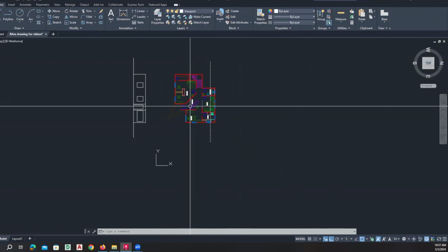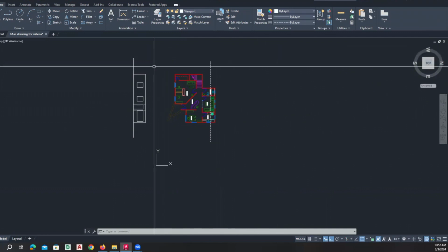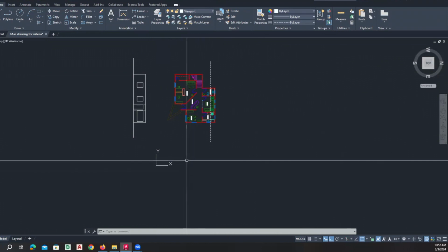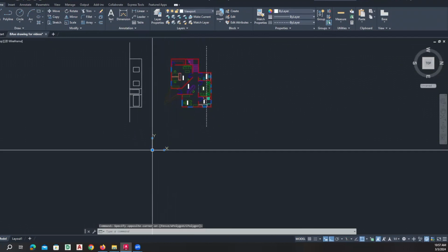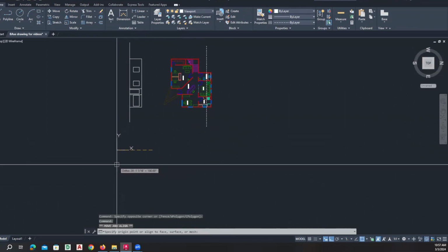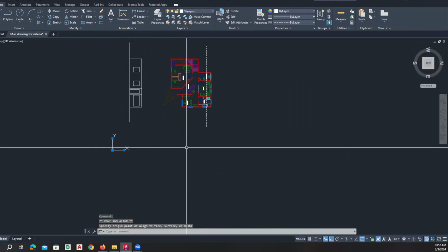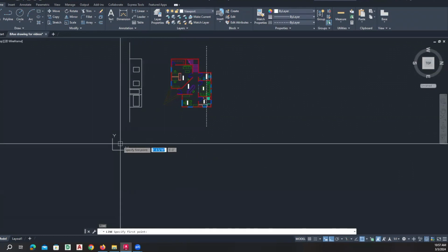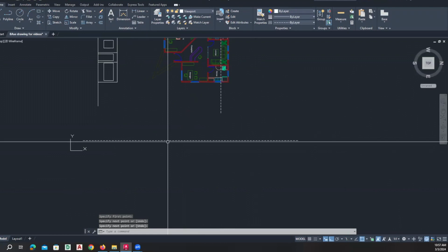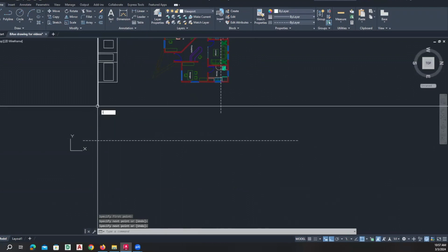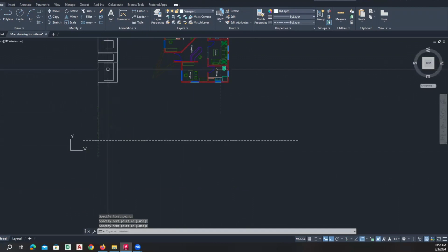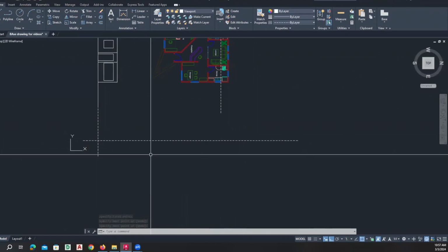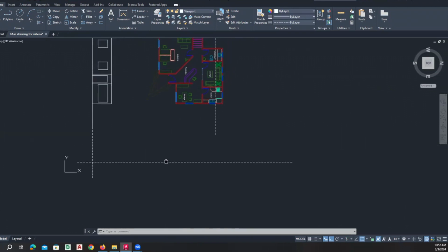So it's always remaining the same, except now I changed my view to be parallel to the current UCS, my user UCS. So once I do this, and let me move this over to the side so it's out of my way. Now what I can do is draw a ground plane here. And I'm also going to extend my ground plane from the previous elevation so that it intersects this ground plane as well. And I'll tell you why that is important.